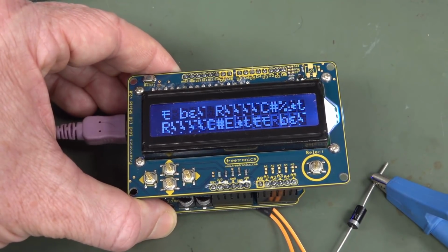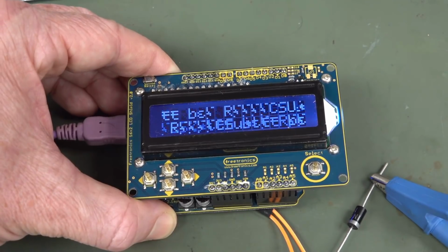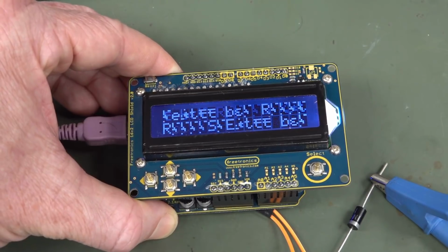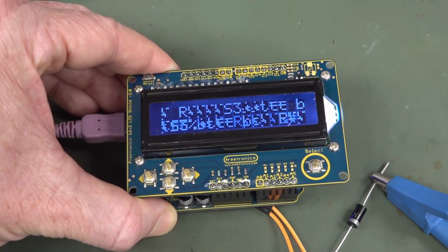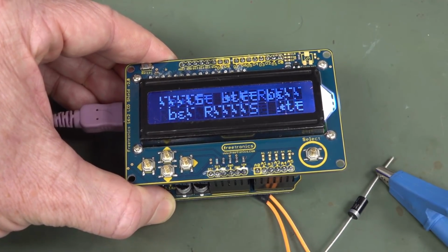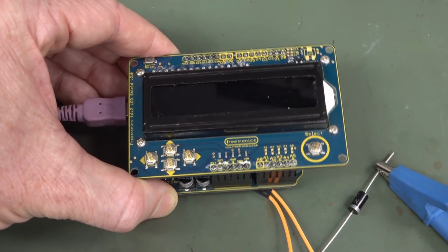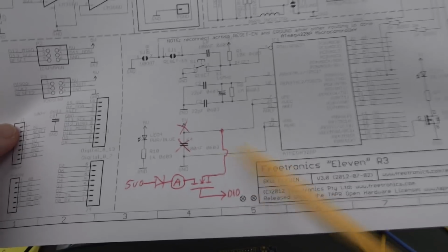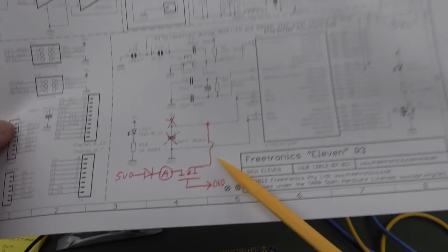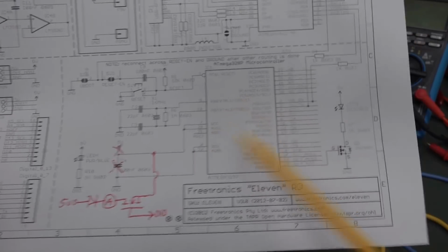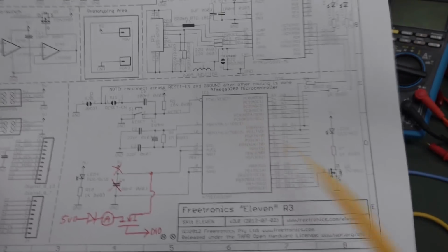There's a limit to this, so don't expect this thing to work in every situation. In fact, I wouldn't recommend you use this in a production environment, that's for sure. But who would have thought you can actually PWM a processor's own power supply? It sounds nuts, but it works, kind of well. That's my power bank again. And as I explained, this will not work if you put a bulk capacitance on here. It's just a silly idea to try and PWM the power of a complex device like this. It only happens internally with the magic of diffusion capacitance.